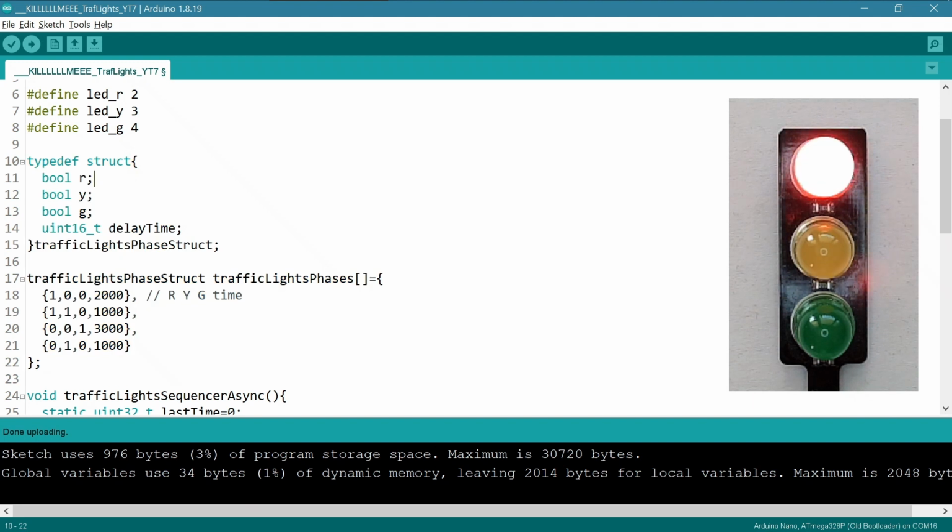We declare a struct over here, and in the struct we have some bools, and we have a uint16. This sounds like a pretty good way of using space, because one bit, 2 bytes. Well, not exactly. This is an Arduino thing. Every bool over here, which is 1 bit, is stored in a byte. So we don't have bits here, we have byte and double byte. This takes a lot of memory. Can we store this more efficiently?